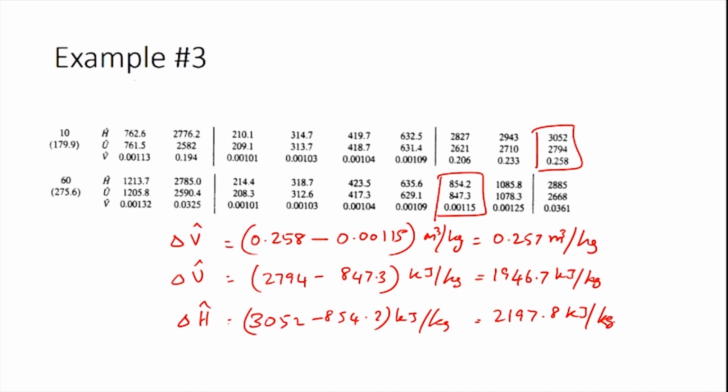the boiling point for the superheated steam. Dew point would be the point at which condensation happens. Here the superheated steam state is 300 degrees Celsius and 10 bar. So, going back to these values here, you can find the boiling point as 179.9 degrees Celsius, which is also the dew point or the point at which condensation would happen.